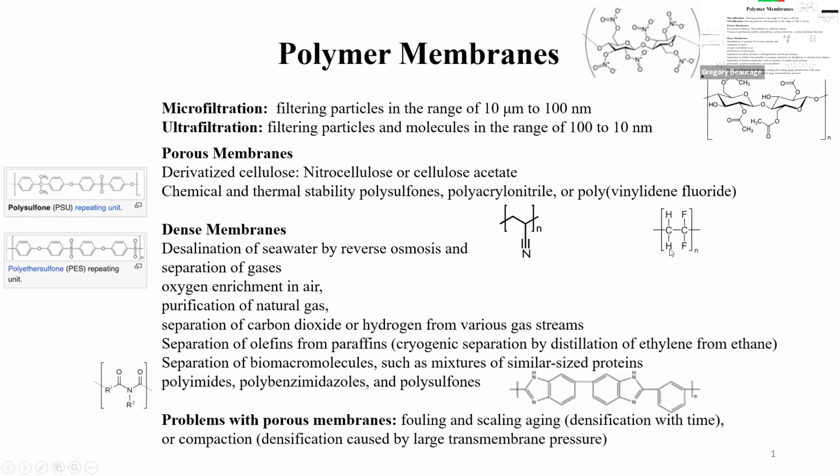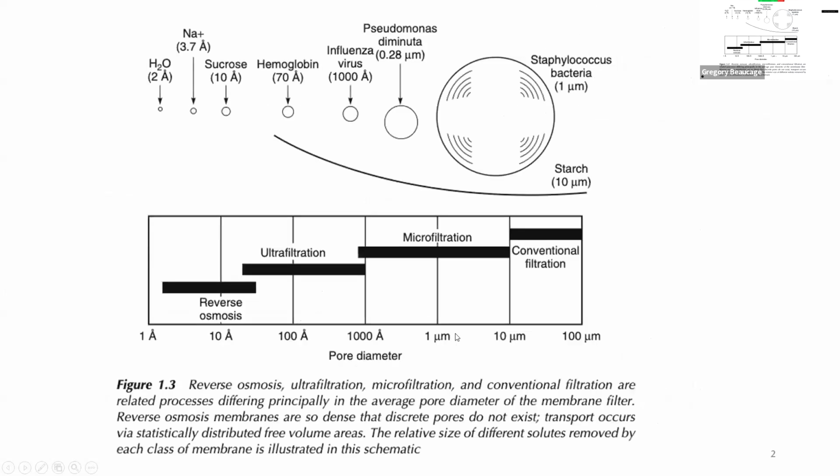Vinylidene fluoride is a high strength polymer. It's used in batteries because it's got the polar groups. That's like a battery separation membrane type material. So you generally want to have thermal and physical stability. That's kind of the things you want. And a lot of the same polymers are used for the different kinds of membranes. It's basically all strong polymers, some polar, some non-polar, to separate different materials. So yeah, that's kind of that business.